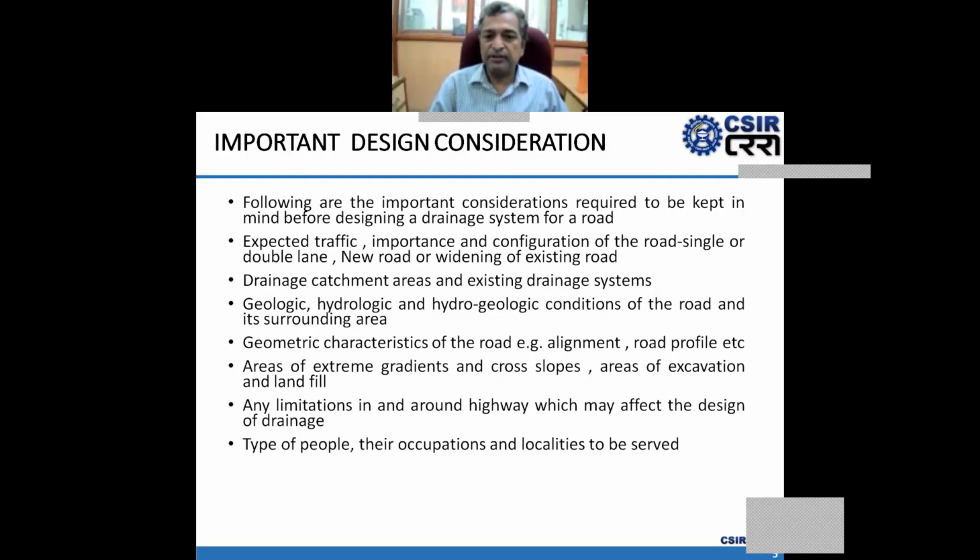We should consider the drainage catchment areas near the road alignment and the existing drainage system before designing the drainage system.